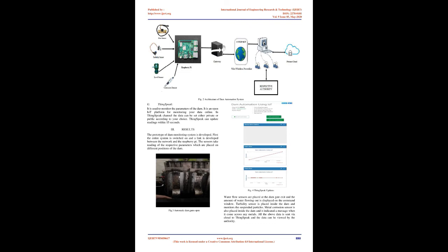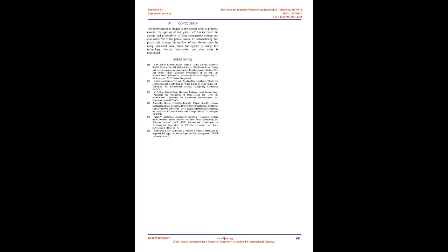D. Water level sensor. The level sensor we are using is known as a conductive sensor. The liquid which can conduct electricity can be used in the sensor. When a conductive liquid reaches some point, it will come into contact with both the longer and shorter electrodes, and thus completing a circuit and activating an internal switch.